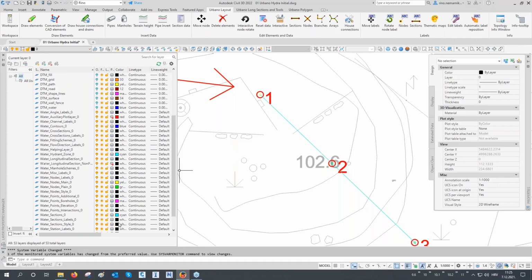But this is not recommended, because if you do it with AutoCAD, you will just change it in your current drawing. Later on, you can export from one drawing and import it to another drawing, and then merge multiple systems and so on. Then these colors will not transfer because they are saved only in the DWG.